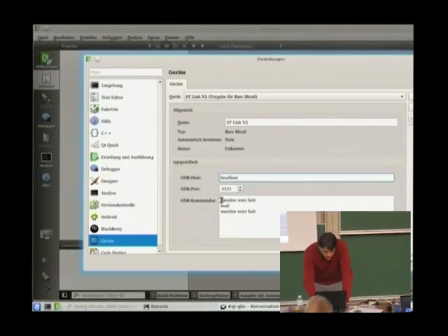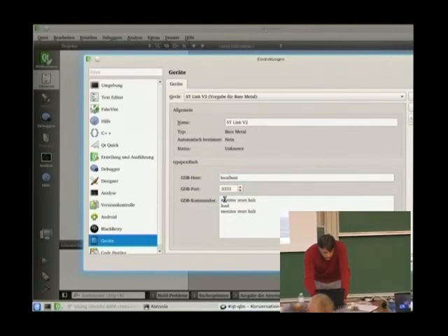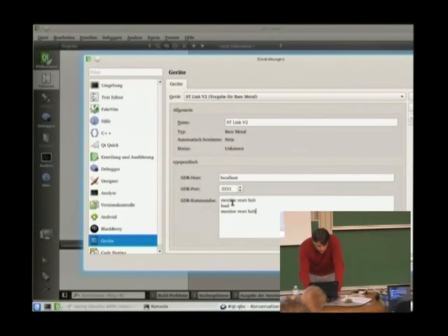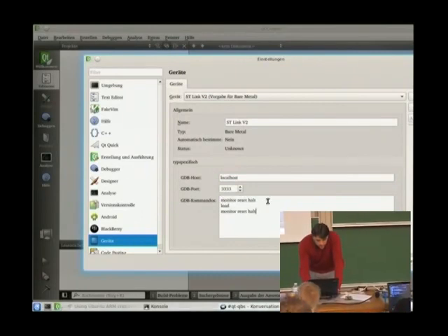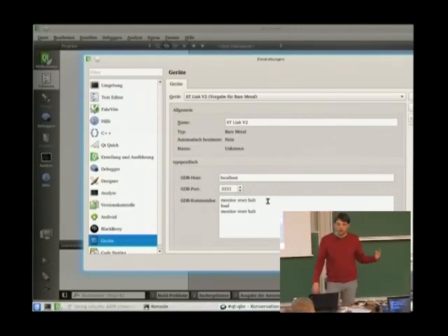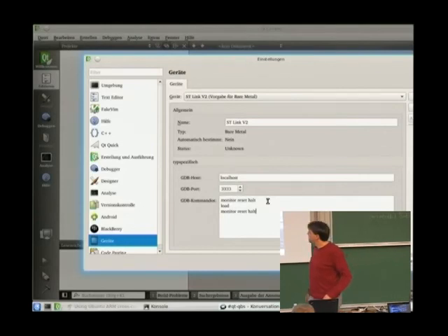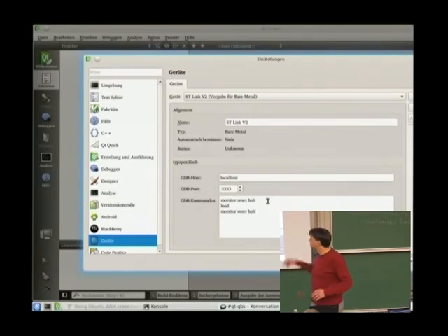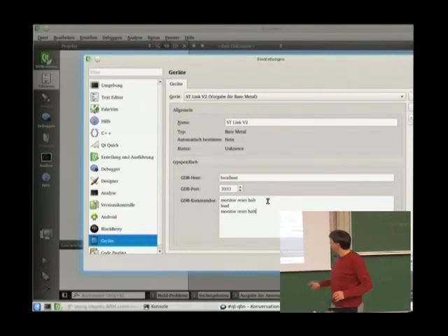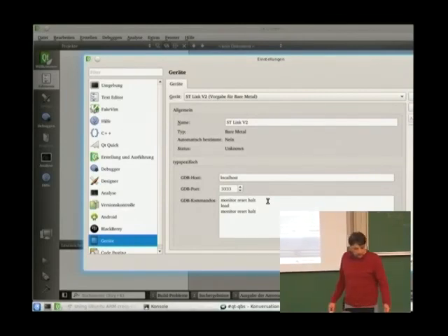So down here are the commands for OpenOCD. Typical commands to get the program loaded are to reset the device, load up the binary into the hardware, and do a reset again to make sure it's in the proper state after loading. Normally it's not needed, but that's all you need for getting the device programmed and up and running on this side.